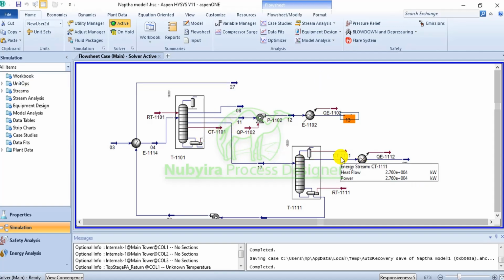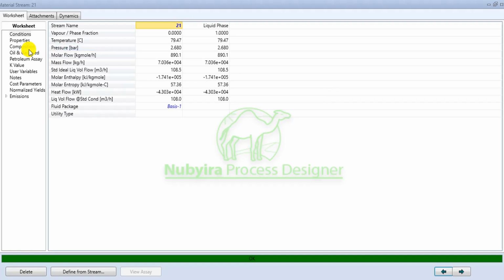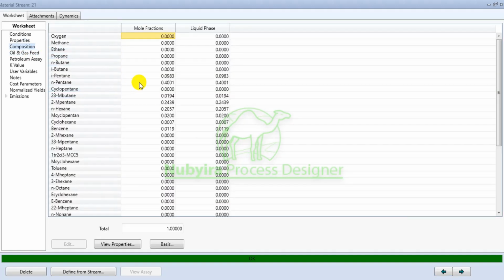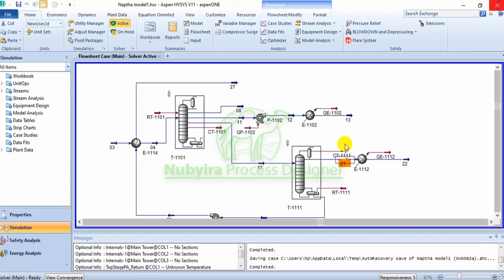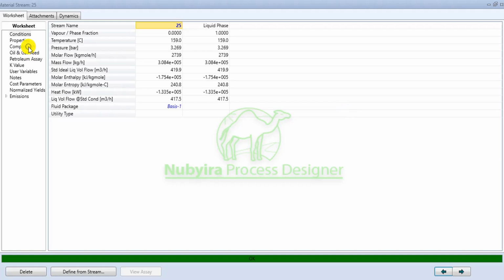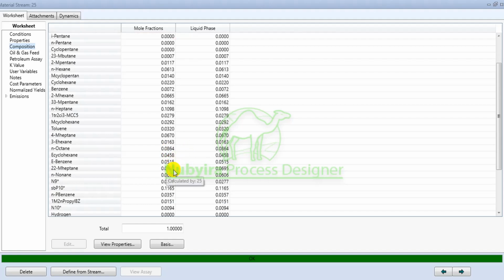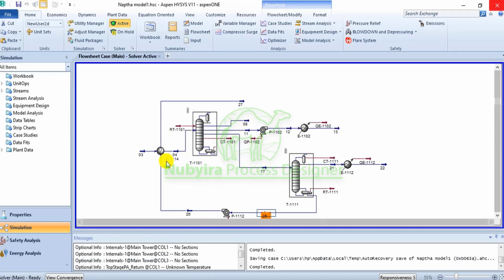Then you split the remaining naphtha into two more components that we have. We have mostly pentane, and some hexane here. Then this will be the more heavy components, and you have the heavy components of the naphtha stream over here: benzene, heptane, and up to nonane or octane. So that's the naphtha splitter, so you can use both of the streams in subsequent units in the refinery.